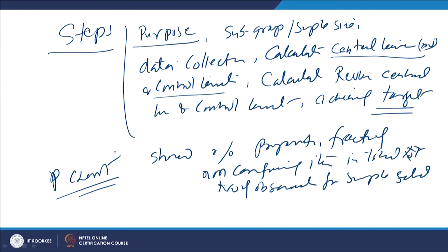Like, say, if you have selected 2000 items from the different samples, and out of the 2000 we have got 200 non-conforming items, then 0.1 will be the fraction p value, indicating that 10% is the fraction of non-conforming items.